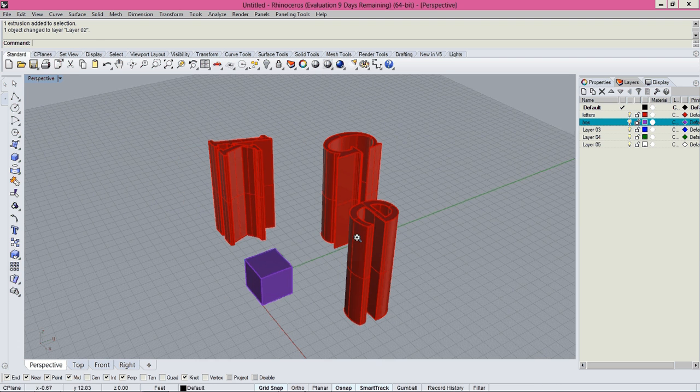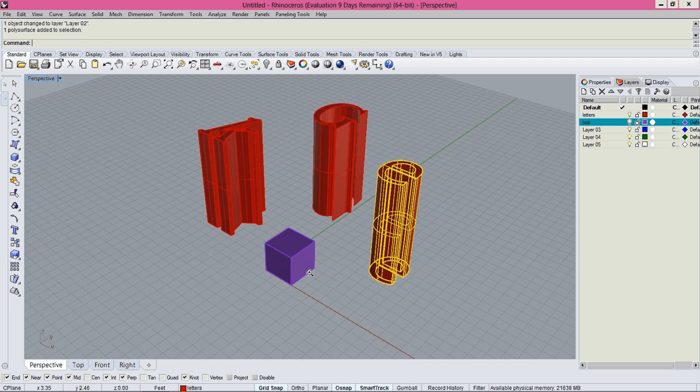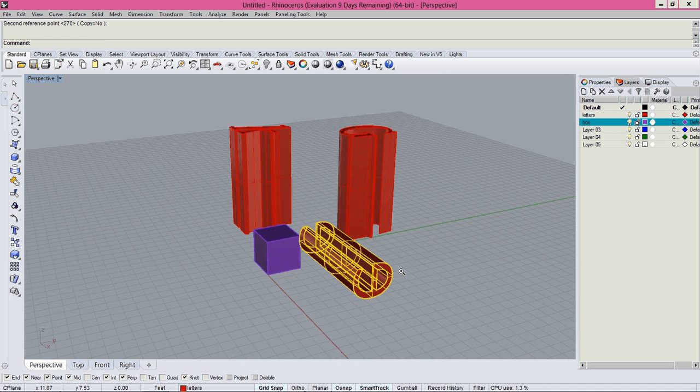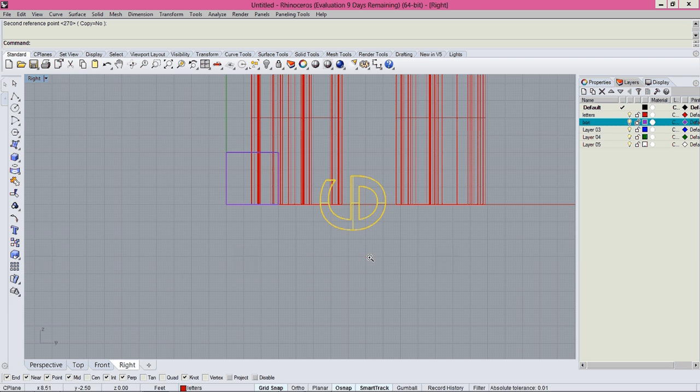Okay, now we have to place the letters in a way that we like in relationship to the box. So what I'm gonna do is rotate several times, probably scale, and then just locate them in the middle. So I'm gonna say rotate 3D, and remember in 3D we give an axis and then a rotation, and then sometimes just go to Control Tab and go to the view where you have that letter, move, put it here.